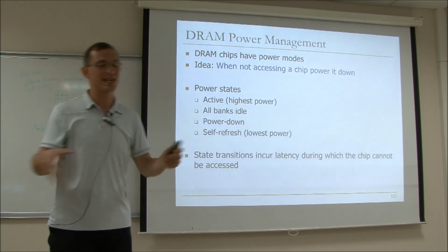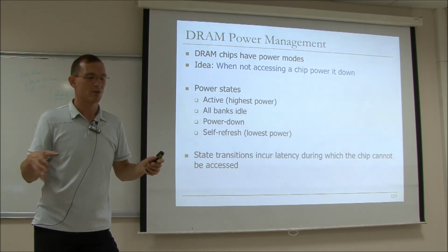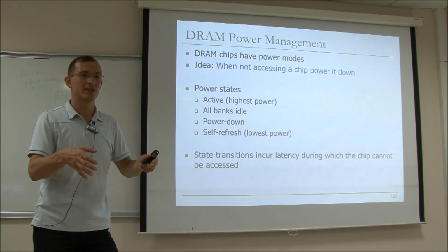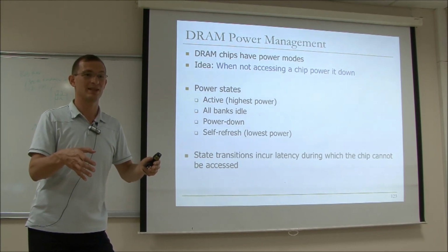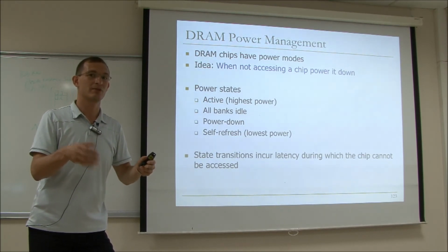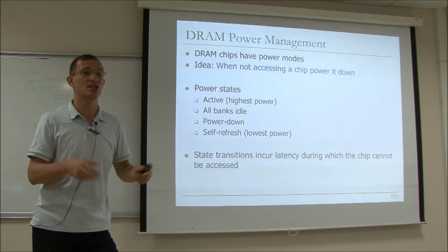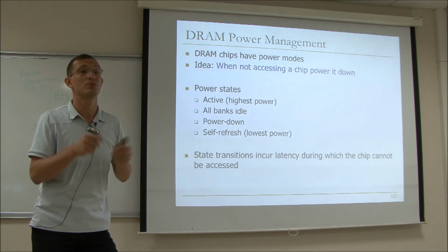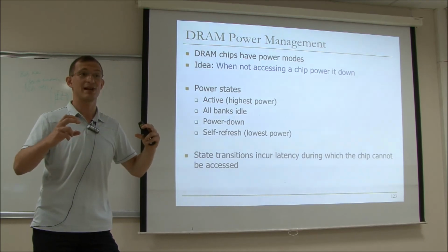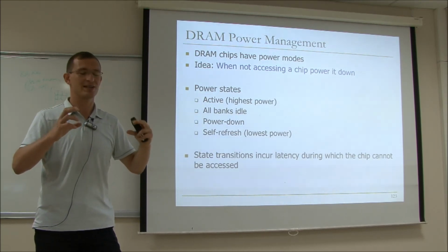The downside of those cached DRAM techniques has been that once you add one more row buffer, it's expensive in DRAM. We've done some studies where the additional overhead of cached DRAM is about 50% of the DRAM chip, because these are SRAM rows.